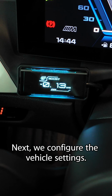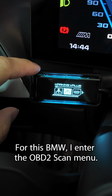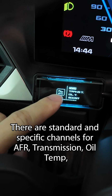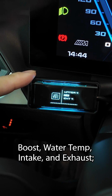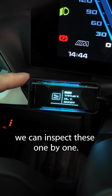Next, we configure the vehicle settings. For this BMW, I enter the OBDII scan menu. There are standard and specific channels for AFR, transmission, wheel temp, boost, water temp, intake, and exhaust. We can inspect these one by one.